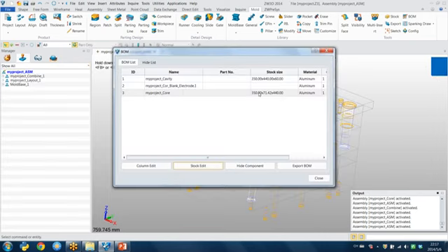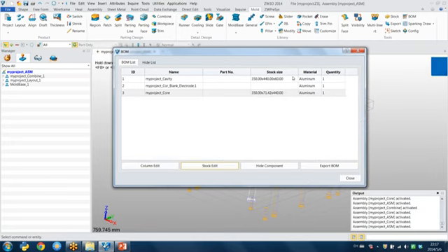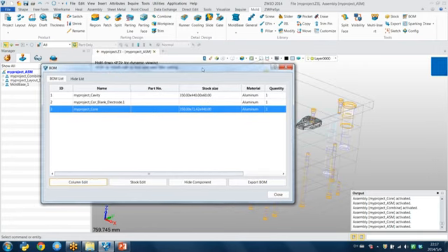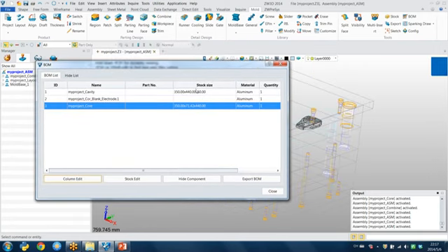So you can find this is the size of the core. This information is very important for mold design. After you finish the mold design, you need to get the size of the stock, so you can use these functions to get the size automatically.